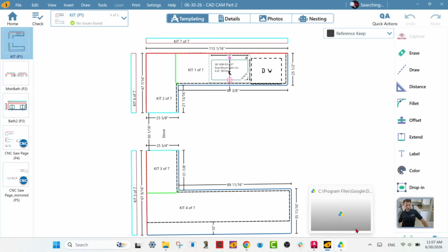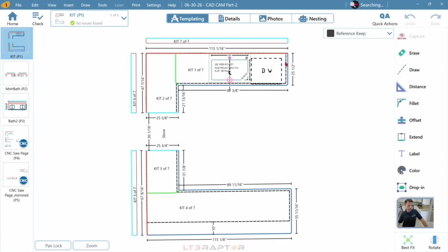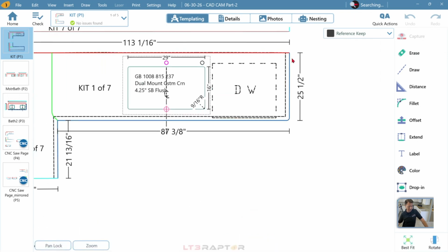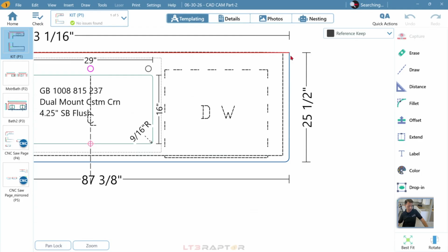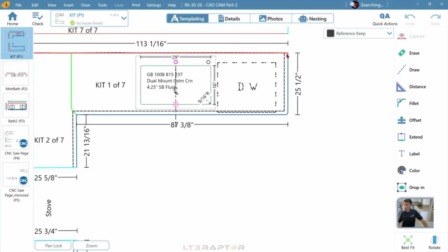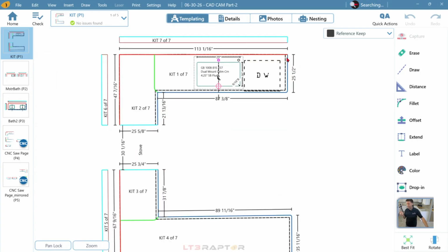Great question. So if this was an OG edge, the extent of that OG edge here, for example, would be a certain amount, but the top of the traditional OG, let's say, might be here. Short answer, no, we don't. Here's the why behind it. We have some fabricators that feel really passionate: I want every splash to be pre-cut and shorter. And we have other fabricators that want every splash to be 2 inches longer for installers, usually an install helper, to cut to fit in the field.